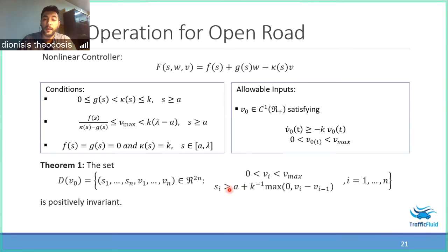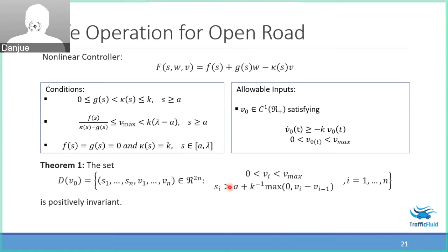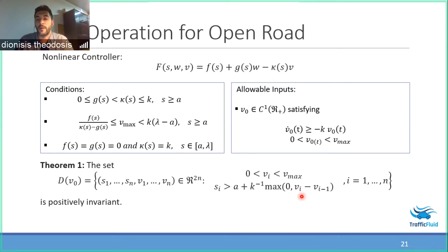If we have a very slow vehicle ahead and it changes lanes directly in front of you, then you cannot avoid collisions. Yes, the initial spacing. Exactly. But notice that if the vehicle in front is faster, you just need very small spacing. On the other hand, if the vehicle ahead is much slower than you, then you need spacing.